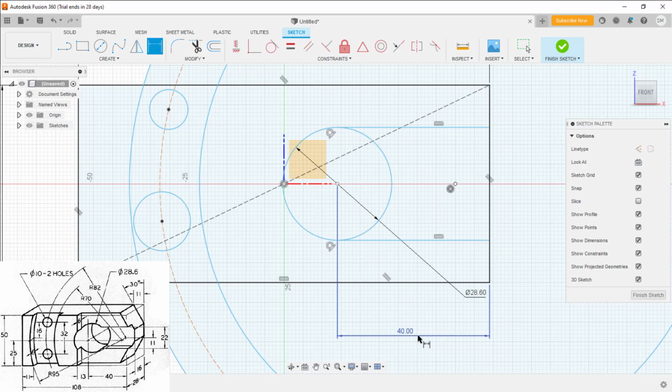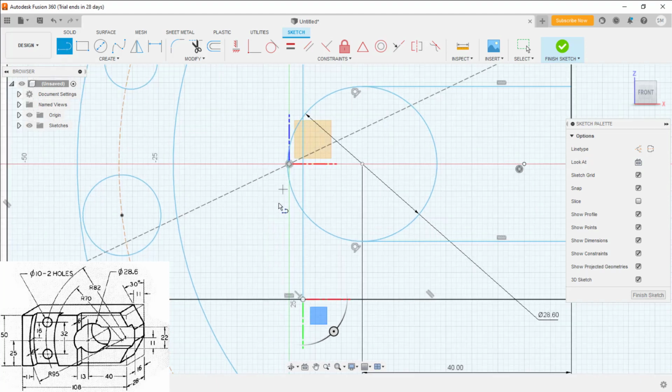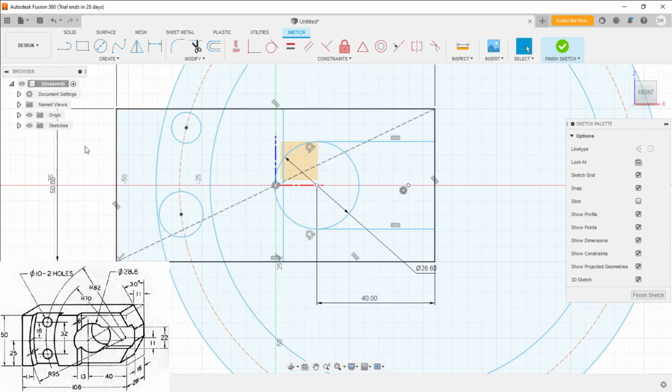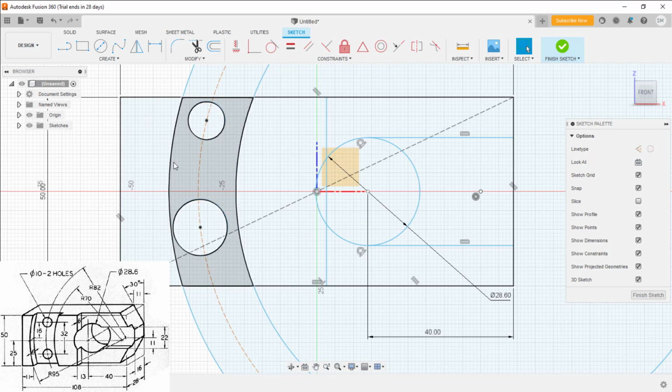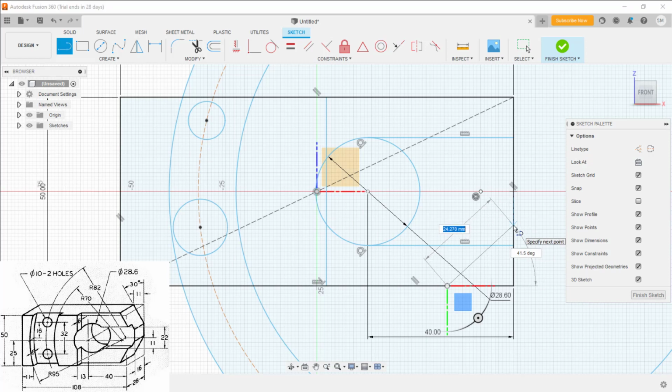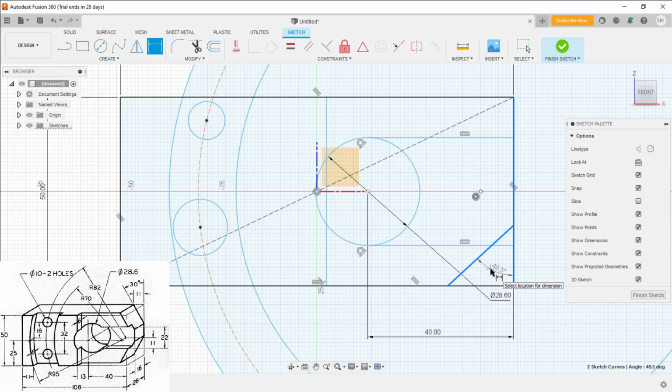Yeah, so next thing, it is still undefined. From this to this one line I'll draw because this is needed here. Yeah, so now let me just draw this diagonal at the corner. I can't apply the chamfer here because it will take a different direction, so I'll do it manually. This dimension is 30. You can even try with the chamfer, that might work, but here I'll take it manually.